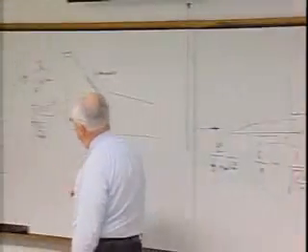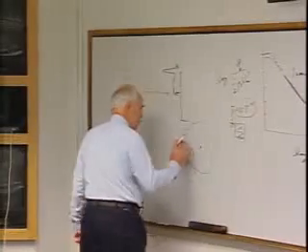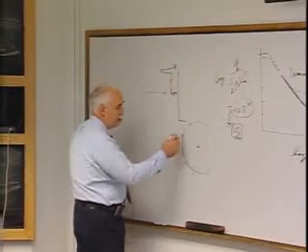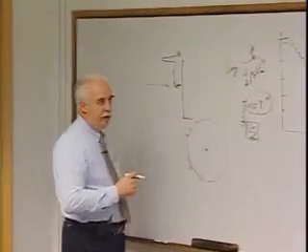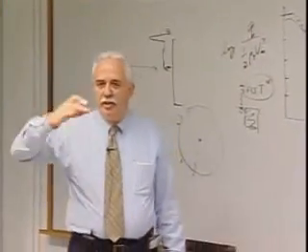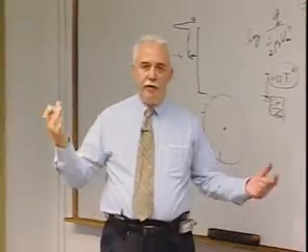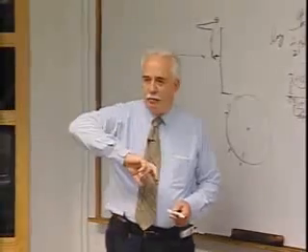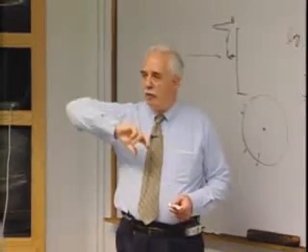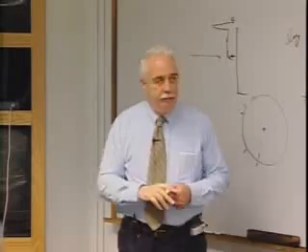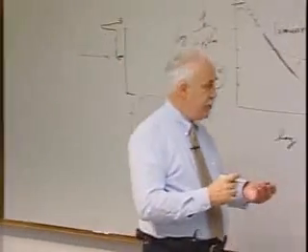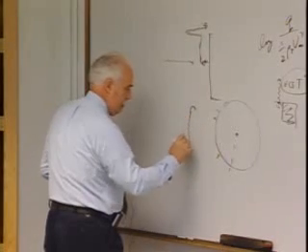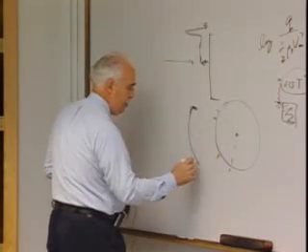So you want to give it some curvature, not only from the standpoint of stability, but also from the standpoint of the heating distribution. And indeed, if you look at the Apollo at zero angle of attack, it pretty much has almost a uniform heating distribution. That's very efficient. I can design my thermal protection system to be so thick, and I manufacture it, produce it over the entire surface exactly the same. That's wonderful, except I still have the corner problem, and so I round the corners a bit.